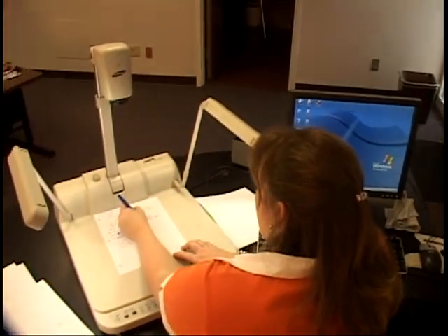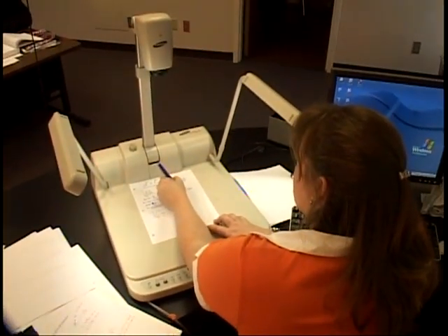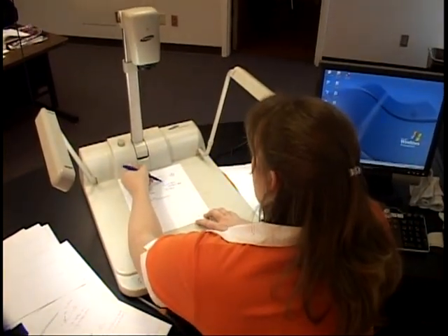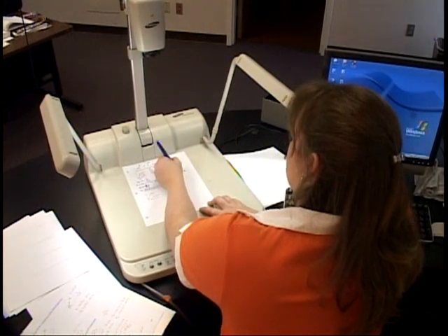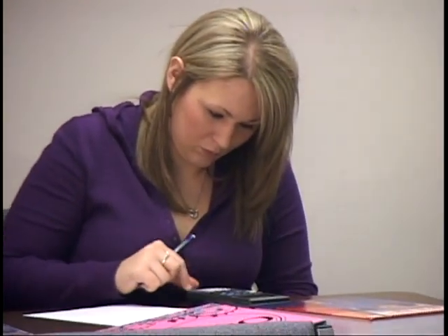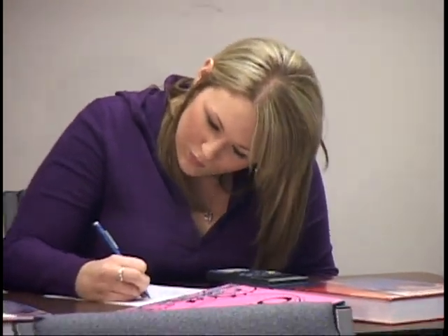And for the component in the y direction, you take the force, 75 kips, times the piece of the triangle in the y direction, so this time 3, over the hypotenuse. But I always like that way better. Everybody understand where all the fractions came from, how to find a hypotenuse, common right triangles, all the stuff we talked about last time?